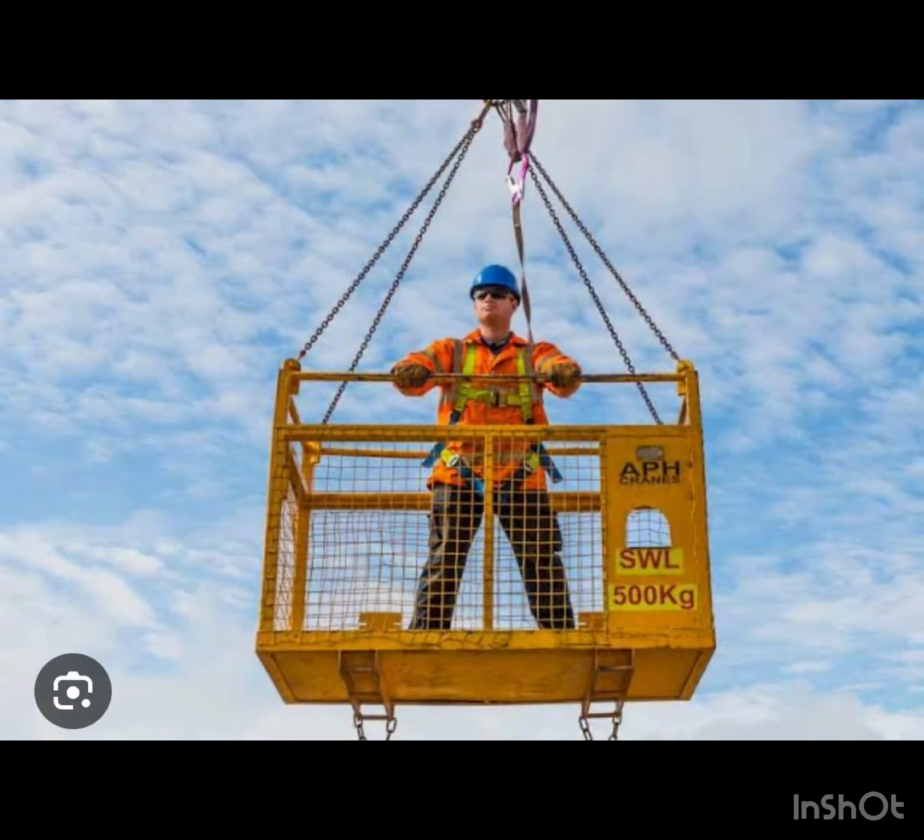What is a man basket and what are the safety measures used while using a man basket? A man basket, also known as a personal basket or man cage, is used to safely lift workers to elevated positions. It should be designed and fabricated according to the standard. It should have a third-party certificate. Two guide ropes should be used, along with shackles with cotter pin. Certified rigger should be in place. Ensure there is a lifting plan, and the load bearing capacity should be written on the man basket.